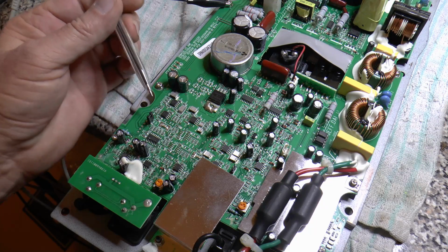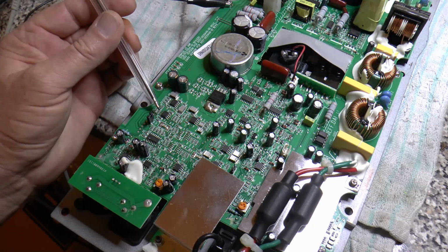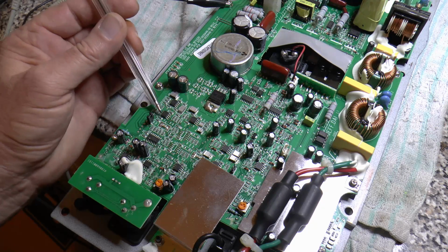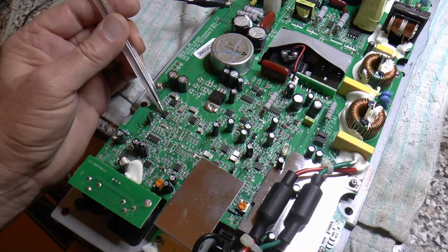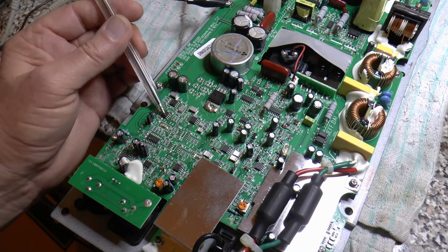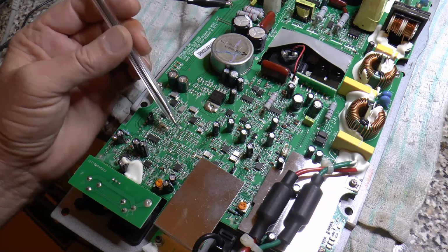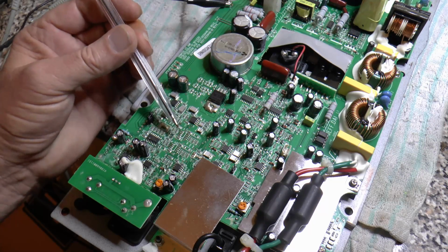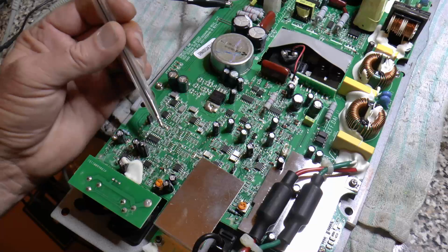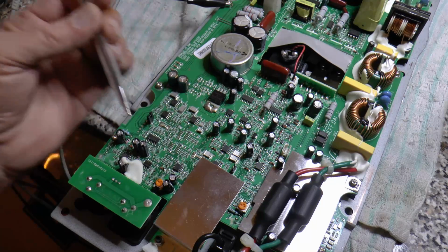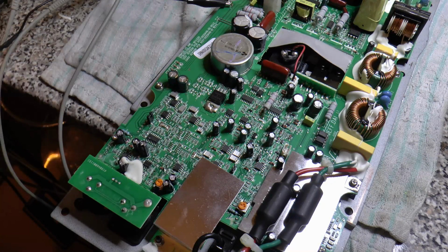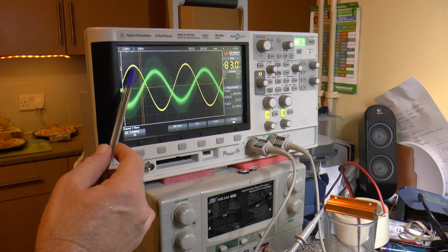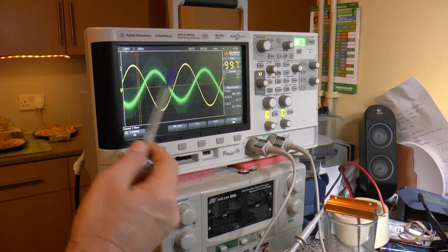And maybe you know, maybe you don't know, anytime you go through one amplifier, there's a propagation delay. So because there's 2 amps inside these op amps, you've got twice the delay. And you can select various amps and actually get an amplifier to give you a specific delay. If you don't want delays, you just spend more money, get faster chips. So obviously the root of any good amplifier is to have the bass in phase with the treble.